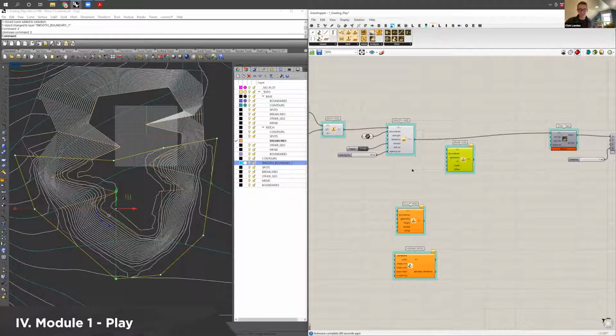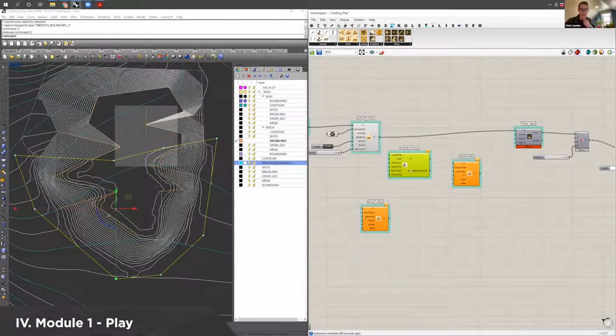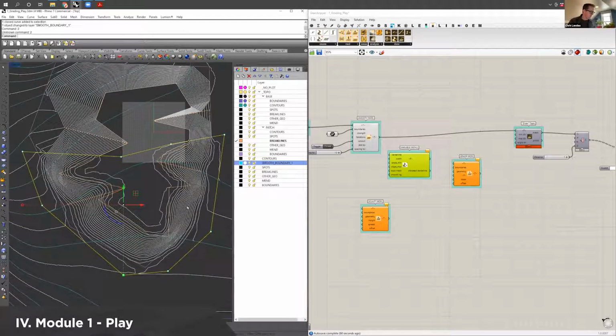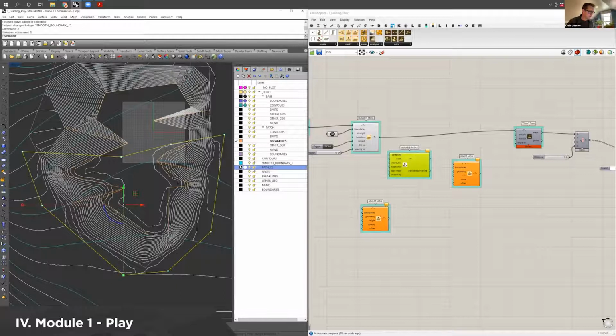But what am I going to grade in there? Well, before we use the grade mod, let's draw a path using the variable path component. So I'm just going to create a new layer here called path_CL, and I'll make that bright purple. And I'll make sure that's the layer I'm working on as well. So I'll do a polyline